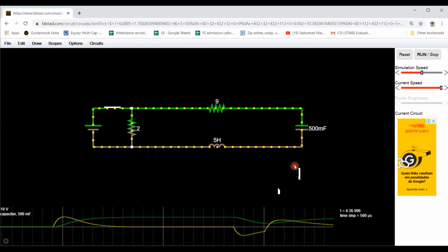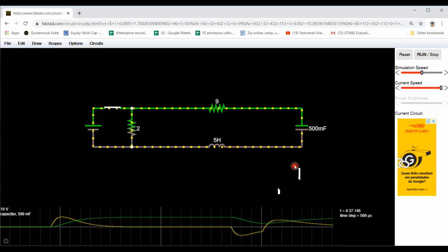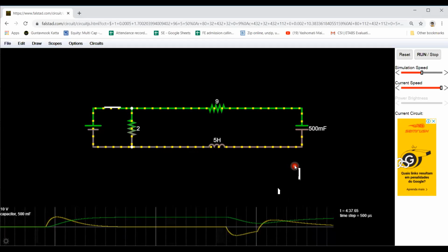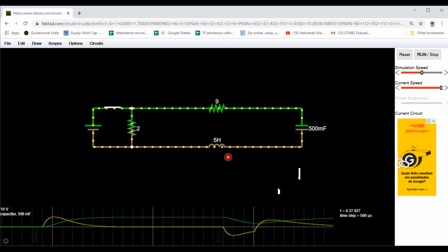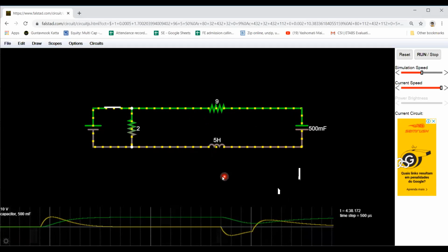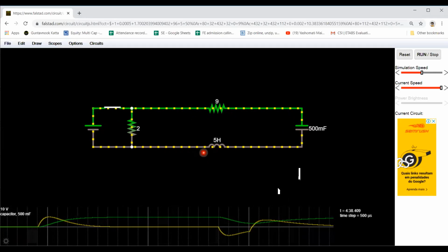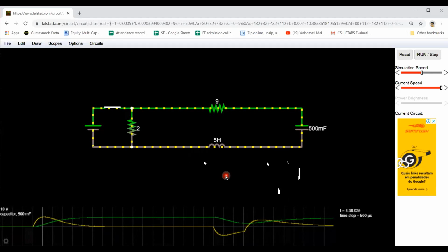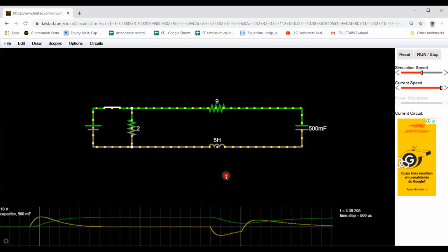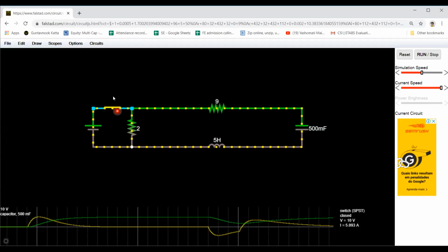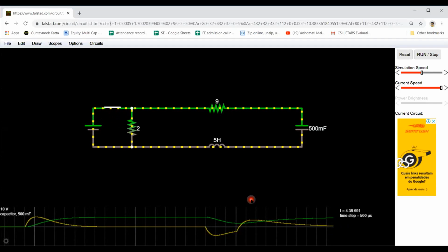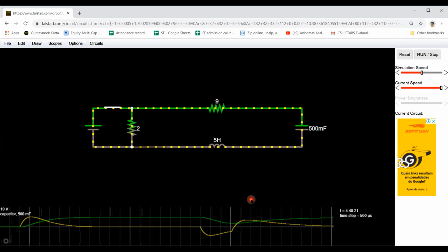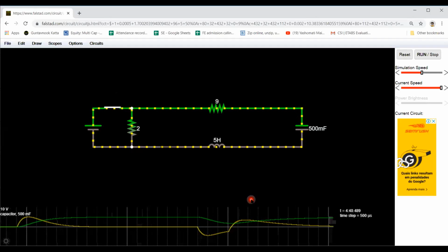While repeating the practical, you allow the system to settle down. That means whenever the current flowing through this particular circuit becomes equal to 0, that is, whenever these yellow dots totally stop, only then try to change the position of this switch, either switching it on or off. Then you will clearly observe the changes in the response.